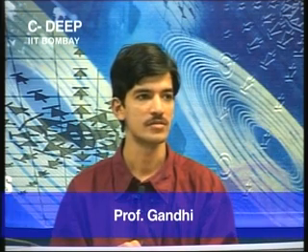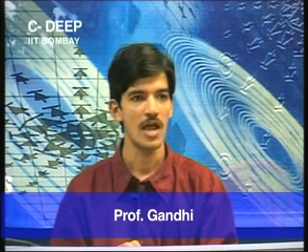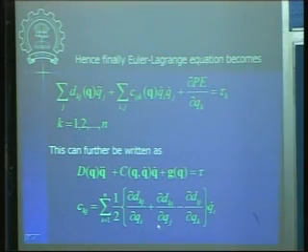So you don't have to carry out all this differentiation every time. You can just find this D matrix from your energies and then use that in this form to get the final expression for the equation. So that reduces your task a lot. So what matters now is finding the kinetic energy and potential energy of the system that we are talking about.